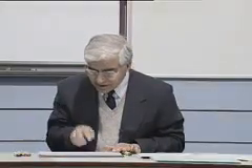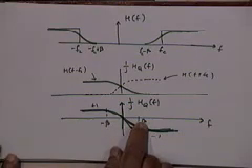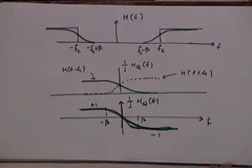Sorry? Yes, the roll off that you will have will depend on the value of beta. If the value of beta becomes 0, you get the single sideband case back, and it reduces to the Hilbert transformer. Yes, please. Sir, in VSB we can't have quadrature multiplexing.